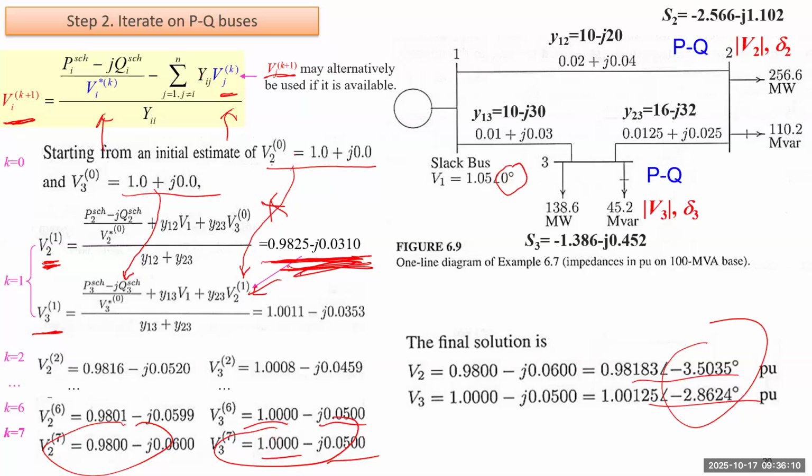So they need to have a slightly negative angle to receive the real power. Another observation is that because both PQ buses consume reactive power, their voltage is also slightly lower than the slack bus. In order to receive reactive power, you need to create a gradient of voltage. In order to receive the real power, you need to create a gradient in angle.